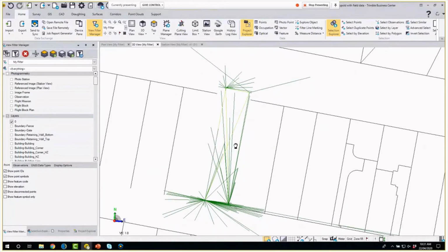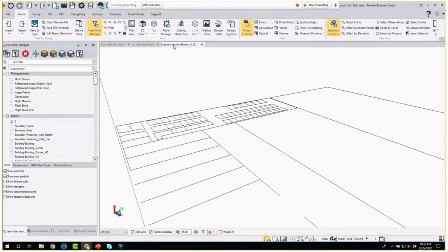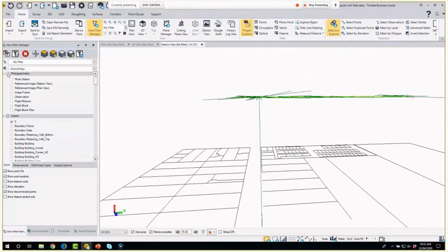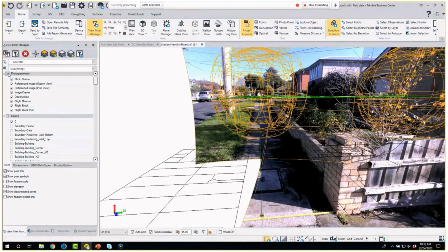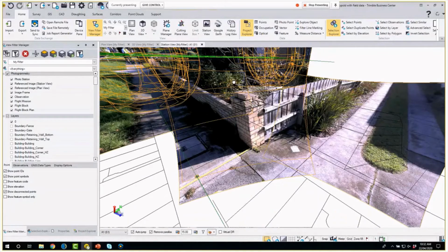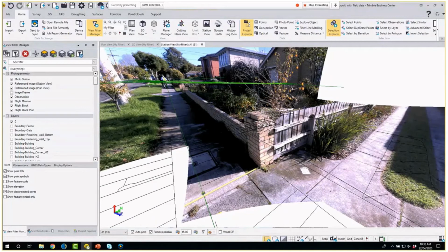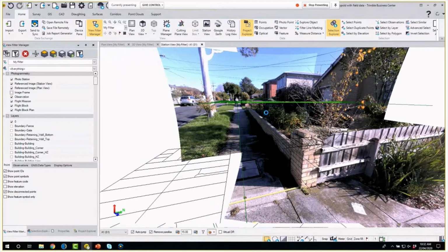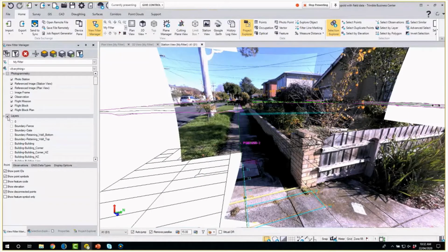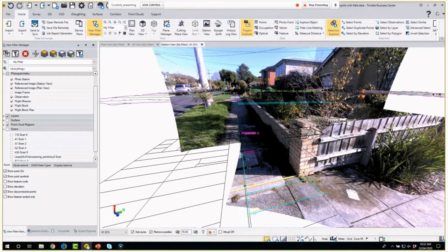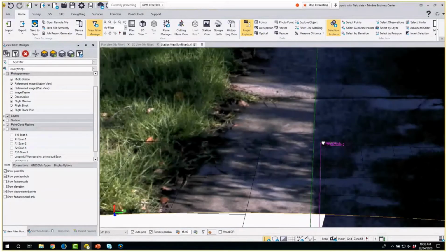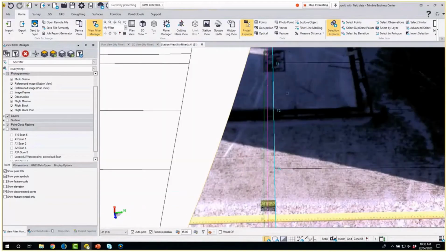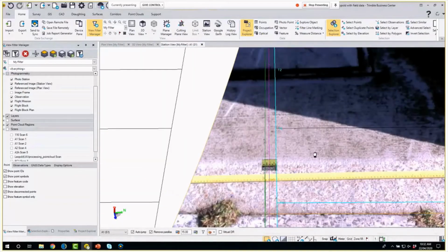But the other benefit here is we're in station view, and if I turn back on our photogrammetry, then we have that, and I'll turn off the image frames. Here we can see all of the vectors and points being overlaid in this view as well, whether they're something that's been keyed in previously. So from an existing survey, I've keyed in these marks, and then I've also got some additional points that I've surveyed where I was taking check offsets.